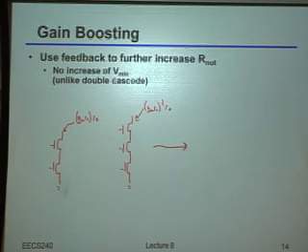But here's where we can remind ourselves how the cascode was working in the first place, and come up with a way that will allow us to improve the output impedance without sacrificing the VDS or the Vmin whatsoever. Okay? So just as a reminder, how was it that the original cascode was helping us in terms of output impedance in the first place?